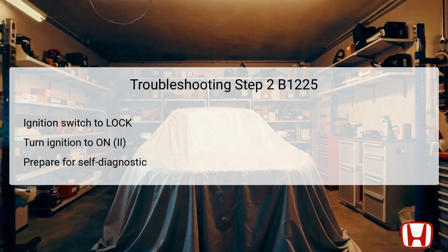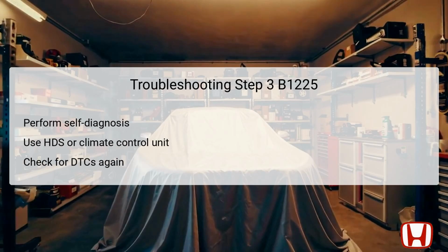Once the ignition is in the on position, the system will be primed to conduct a self-diagnostic function, identifying any current or pending faults in the circuitry related to the temperature sensor. The third step involves executing a self-diagnostic function, which can be performed using the Honda Diagnostic System, HDS, or the vehicle's climate control unit itself.